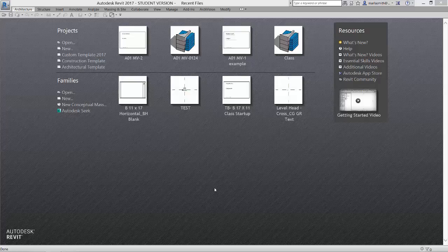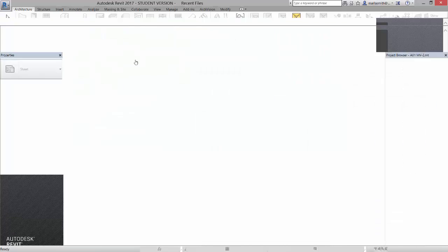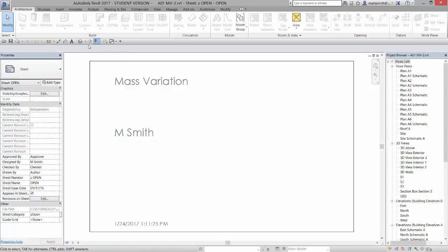Alright, so we are going to put some walls, roofs, and floors by face on the mass that you've created. If you are working on your own mass, you can use that, or else you can download this A01MV-2 that I provided for you on Canvas and YouTube. I'm going to click on that and open it. And I'm going to go to my 3D default view from my quick access toolbar here.